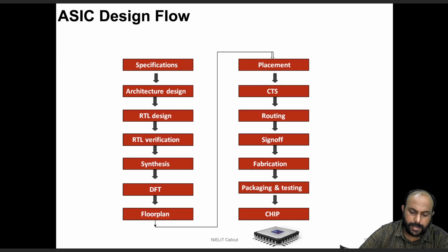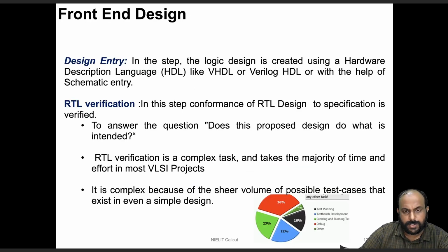After RTL design verification is done, it is subjected to something called synthesis. Synthesis is basically a process of converting your design into a structural equivalent. These two steps, the RTL design entry as well as RTL verification, along with some portion of synthesis, you can call the front end design, because in the front end itself, people will often verify the design on some prototyping platform like FPGA before we take it to a backend design for the ASIC flow.